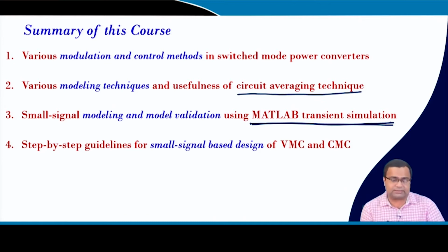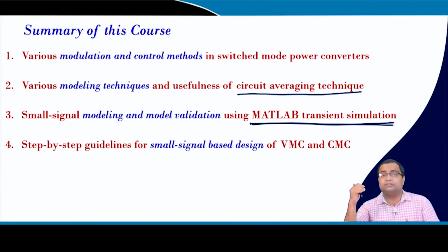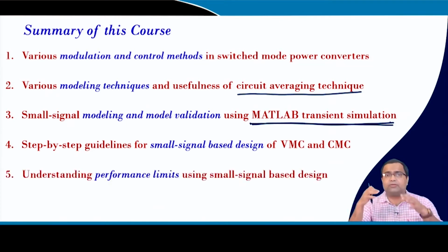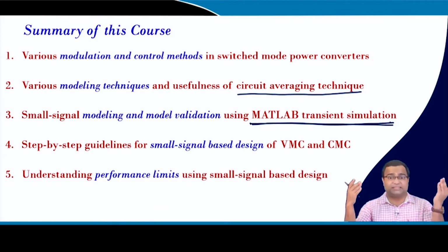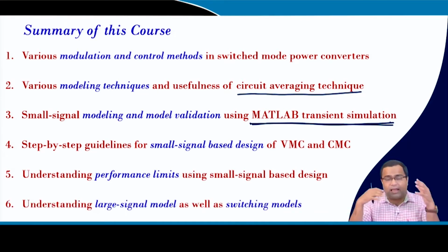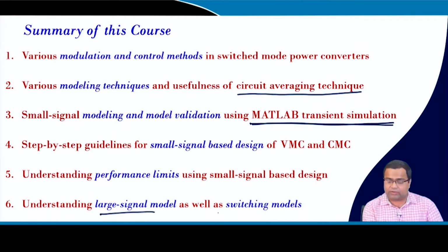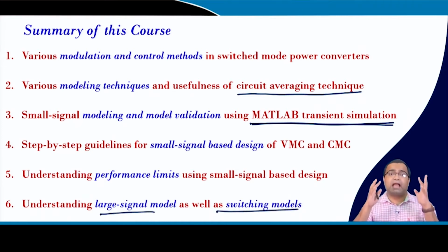Then I have also discussed step by step guidelines for small signal based design and tuning of voltage mode control as well as current mode control. Then we understood the performance limits of small signal based design. Then I have also discussed some large signal models as well as switching models, because the large signal model actually considers both the switching model and the average nonlinear model.